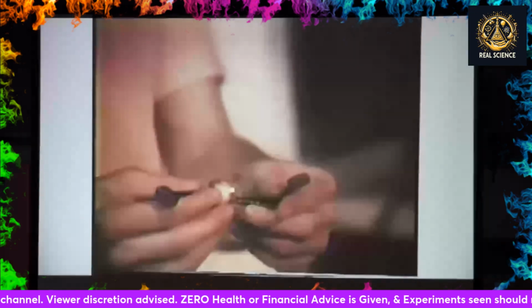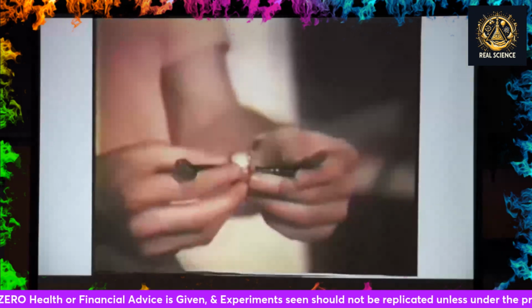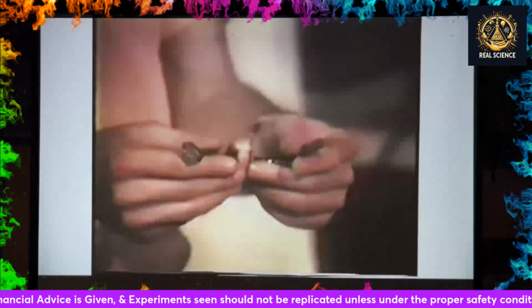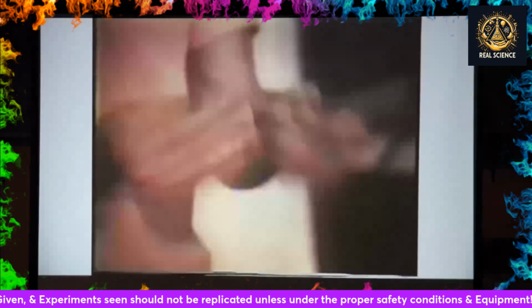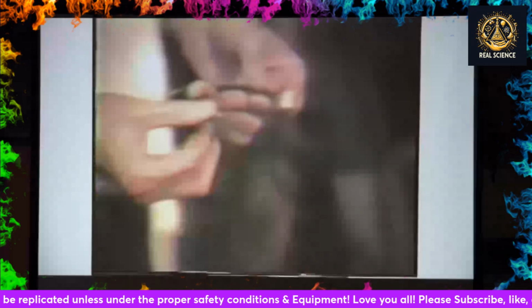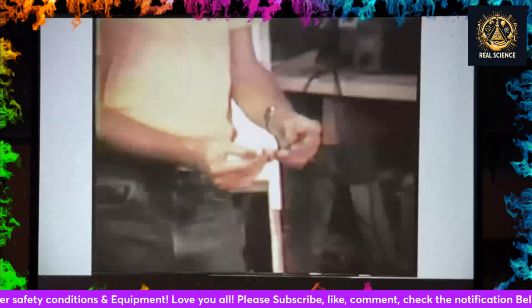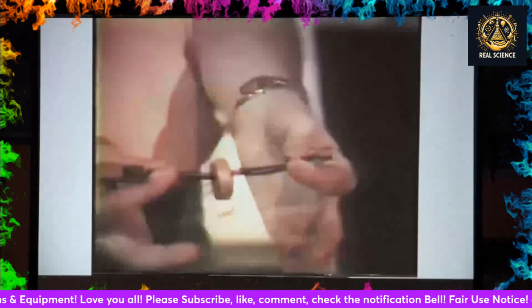Should take a little bit of time to set up, but you said that you witnessed heating of a conductor. Was it that conductor that heated up? This was the one, the very one. Holding it in your hand. What gauge is that conductor? About 8 stranded? Show it to Chris. He would know the wire gauge right off. 10 gauge. 10 gauge stranded. Yeah. Okay, and the length is about what? 5, 6 inches.